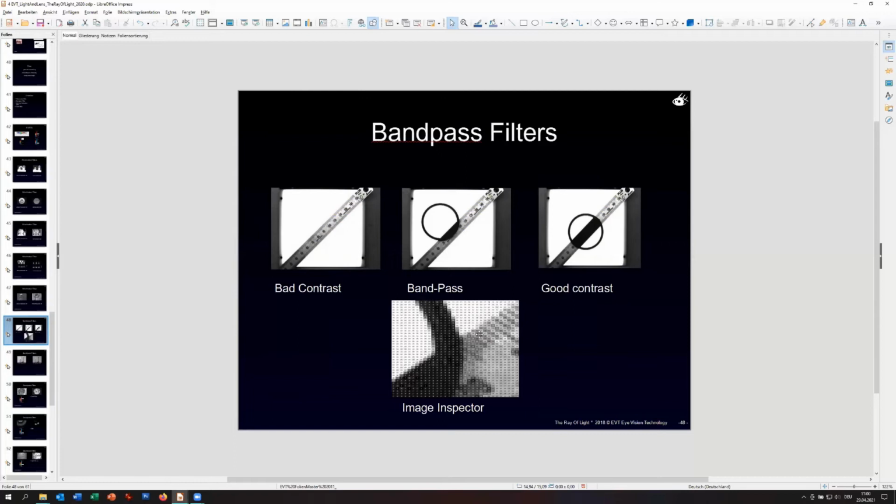So that's why all the stable machine vision solutions try to improve the contrast as good as possible. And mostly the nearly binarized image is the most stable one, because effectively the algorithm has not a lot of decision to see where the edge is. So here it could put the edge 1 pixel deeper or not so deep. And that means at the end you measure different values.